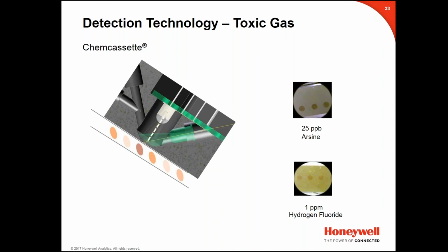So as the stain develops, the reflected light is diminished and reduced, and the reduction of the intensity is sensed by the photodetector in the form of an analog signal. This signal is converted to a digital format, then presented as a gas concentration using an internally generated calibration curve and the appropriate software library.